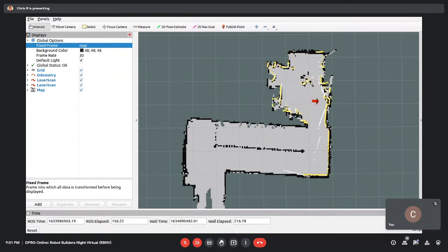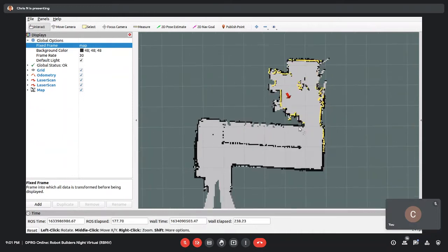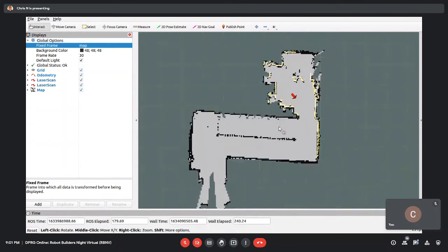That's the stuff that I'm filtering out. Because when the robot's turning and the laser is turning, you get a completely distorted scan. If I were to feed that original laser data directly into this algorithm, it usually gets confused. It would not be building this reasonably decent looking map.